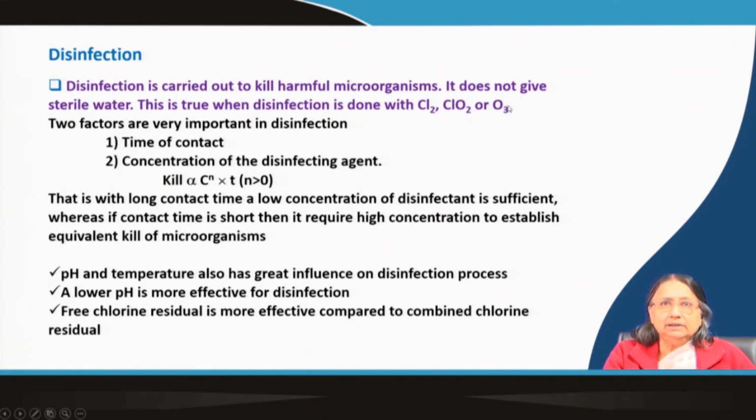These are used in the developed countries, ozone, and this is not much attempted here, maybe some research has to be done, but chlorine is most widely used. In our country also we are using chlorine. Now, and that is with long contact time. This I already explained to you, that contact time and concentration we can vary depending on what we want actually. Okay.